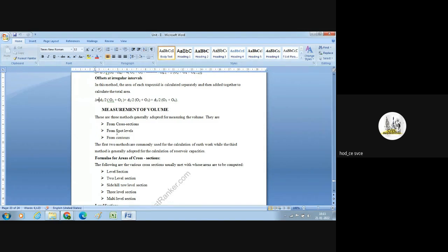Meridian of A is 0, because the meridian at the point A itself is the start. Okay. Next, meridian of B is the departure. Departure is D1. That means 0 plus D1. Meridian distance small m equals half of D1. Capital M1 equals D1. That is the double meridian distance.